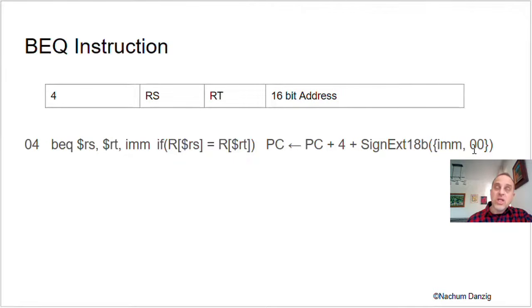In other words, we're reading a new instruction, which means if we were on instruction 1, we're going to instruction 10. But remember, every instruction is 32 bits, which means they're each offset from each other by 4 bytes. Which means if we want to go from instruction 1 to instruction 10, we're actually going to have to go 40 bytes forward. So the way we do that is by shifting left 2 spaces.